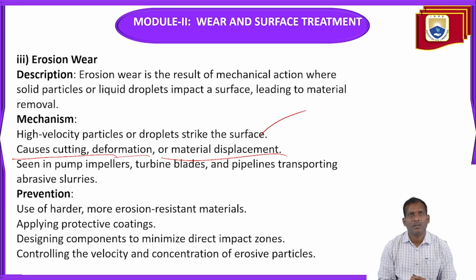You can see in pump impellers and turbine blades, these are frequently subjected to this type of particles. It may be solid or liquid droplets. So this type of impacting leads to erosion wear. Erosion wear is nothing but material removal.